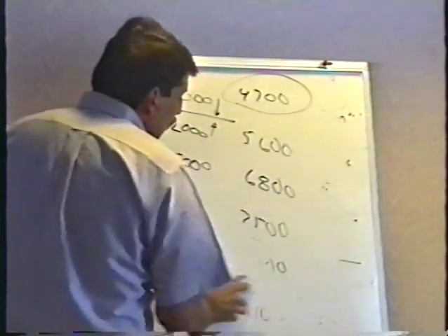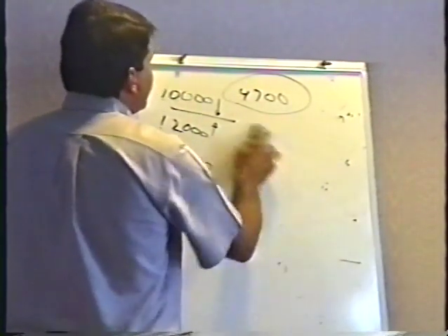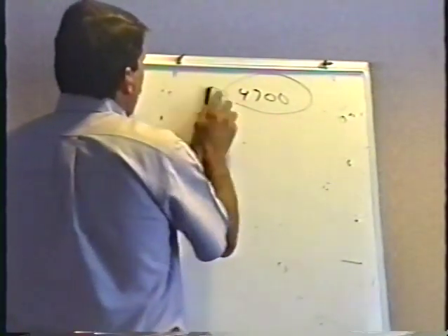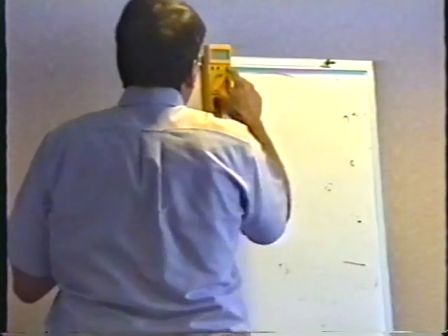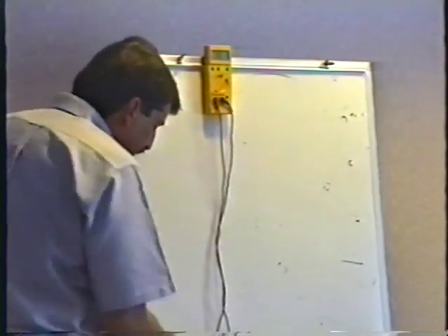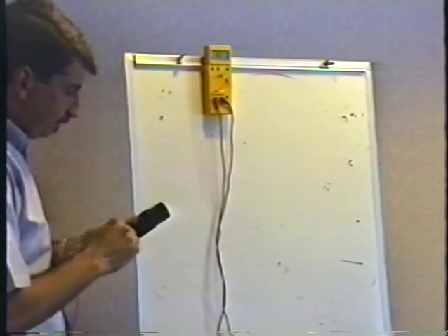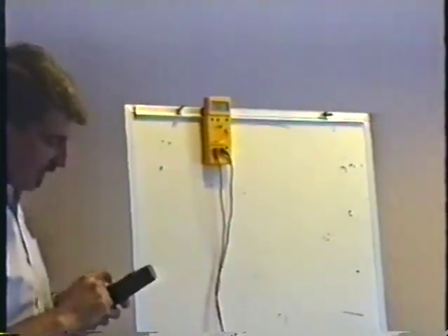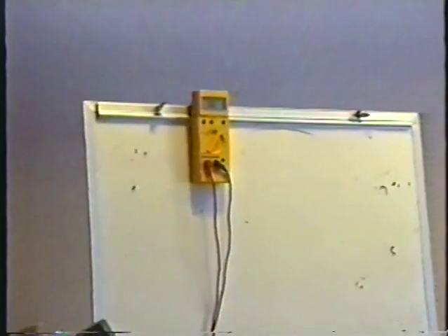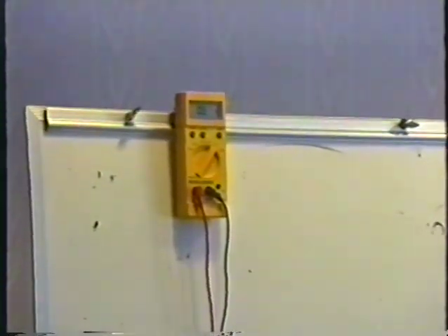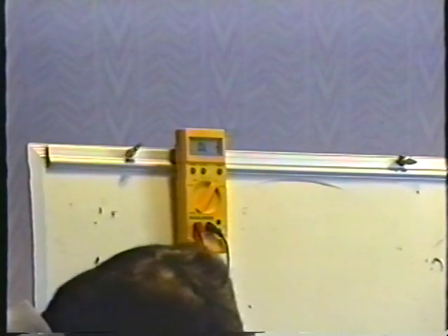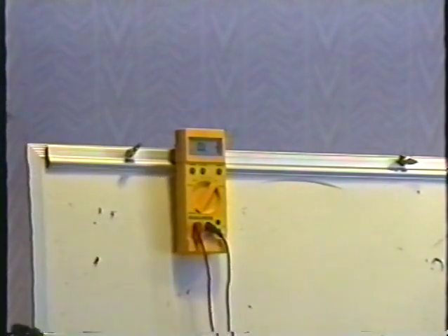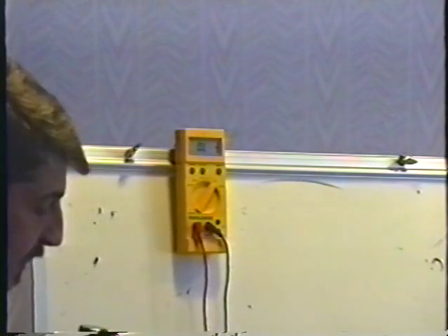Now, when you have a bad resistor, what you'll measure is an open circuit. I put my meter on ohms. I have a resistor here that is supposed to be 2 ohms. It says 2 ohms on it, so you would expect it to be almost like a short circuit, basically. It's only 2 ohms of resistance.